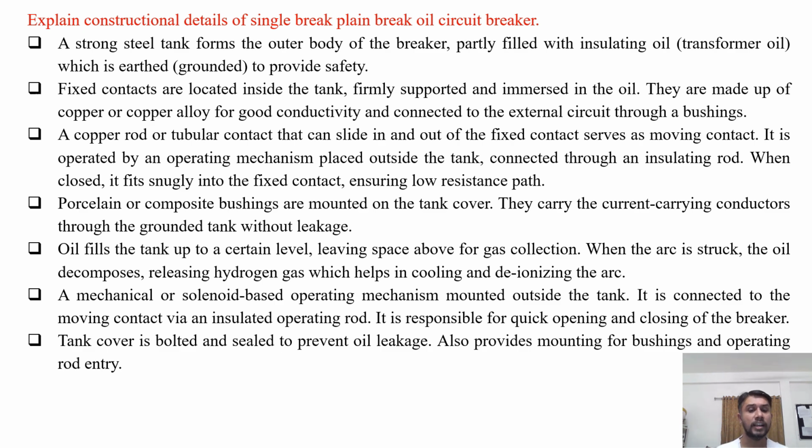Oil fills the tank up to a certain level, leaving some space above the oil level, because the tank is partly filled and some part is serving as an air cushion for gas collection. When the arc is struck, the oil decomposes, releasing hydrogen gas, which helps in cooling and deionizing the arc.